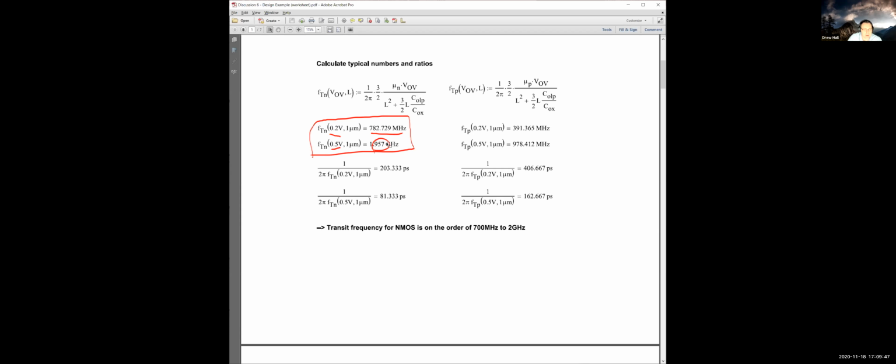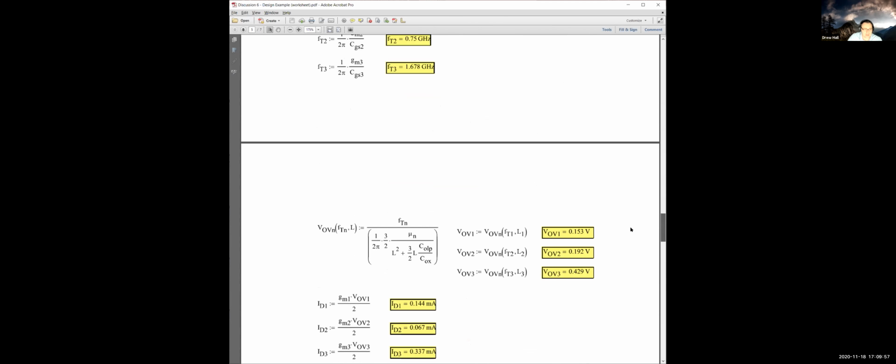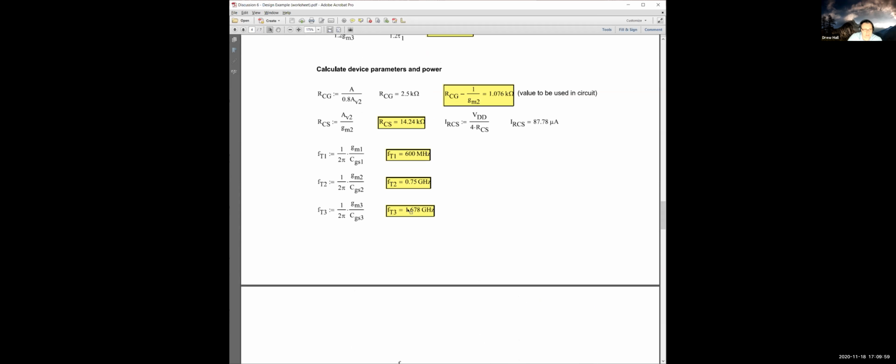And keep in mind that our circuits can't really operate within a factor of about 20 to 50 of FT. And so looking at this, what do we see from these 3 transistors? Transistor 1 and 2, they're not quote unquote working very hard. What about this third transistor though?